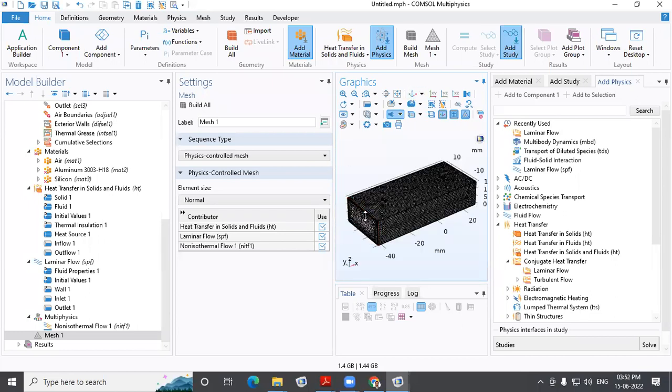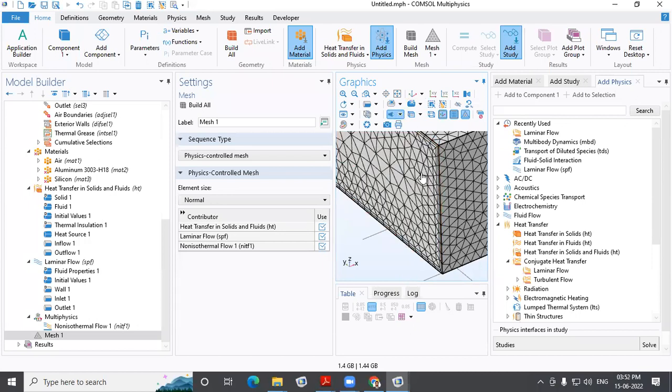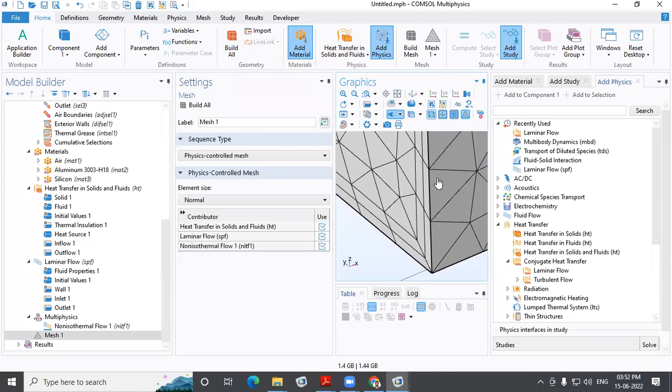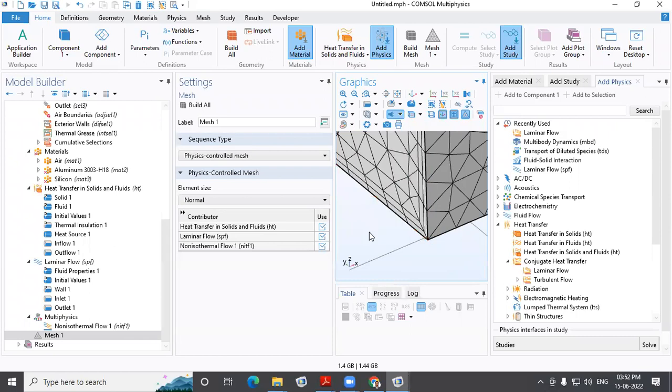So that is the Y plus theory, or we generally keep it to capture the shear stress nearer the walls. So fluid flows against the shear resistance of walls. So velocity is zero nearer the walls, that we all know. To capture that phenomena, we keep the mesh fine there with the help of boundary layers. Okay.